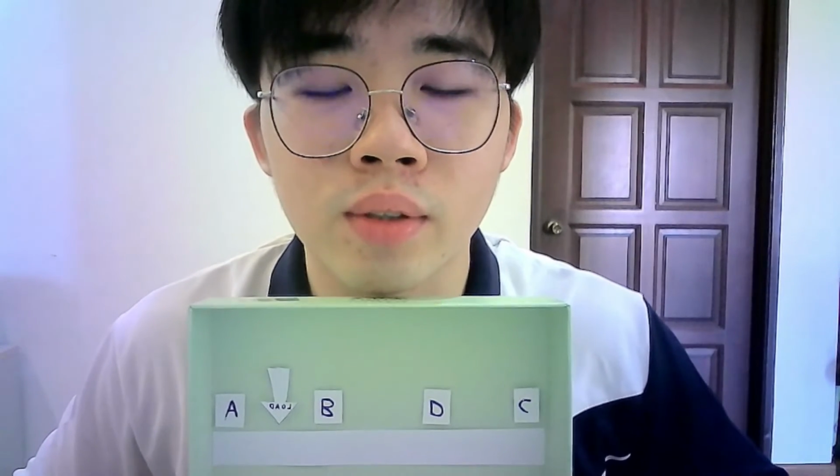Alright, so today we are talking about the shear force variation at a cut section due to the variation of load and also load position experiment. First, the load P is placed at the location between point B and point A. Then the value of shear force at point B, also known as section XX, is measured. After that, the load is replaced by 200 grams and also 300 grams of loads, and the same thing, the shear force is recorded at point B.